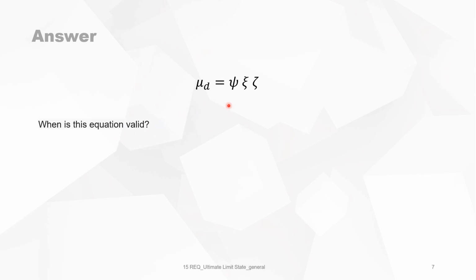When is this valid? Well, the relation is of course always valid in domain 2A for single bending and single reinforcement. We did not use the compression reinforcement, and we did not use an external load to it. So it's only domain 2A that this is valid.